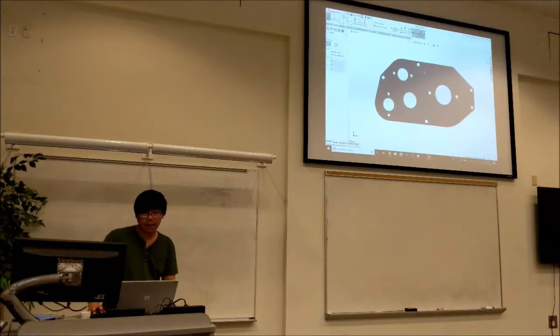But how you do the pocketing in the gearbox is you define everything you want to keep. So we obviously need the outer edge, right? We need something to hold the shape. So we're going to offset the outer edge, and then you can just reverse this. And then you can kind of see the shape, right? That's the material we're going to keep eventually. A good number for that is just 1/4 inch as well.